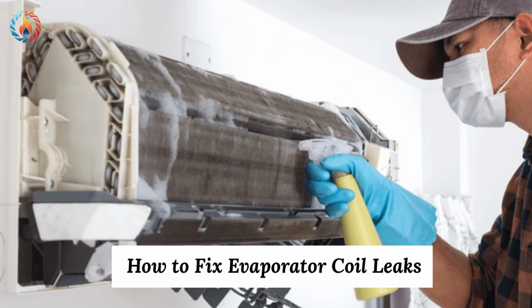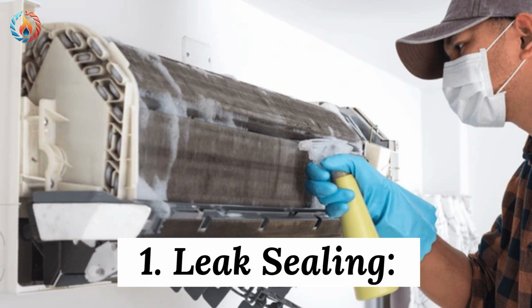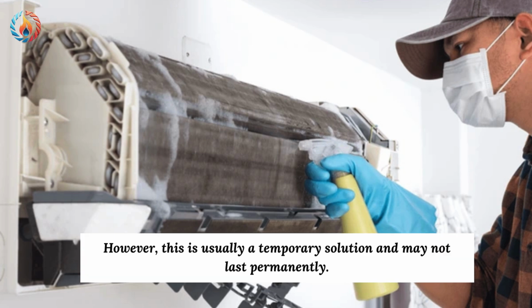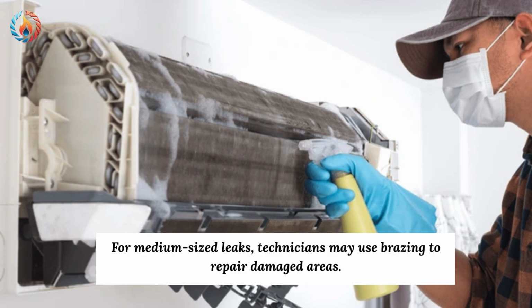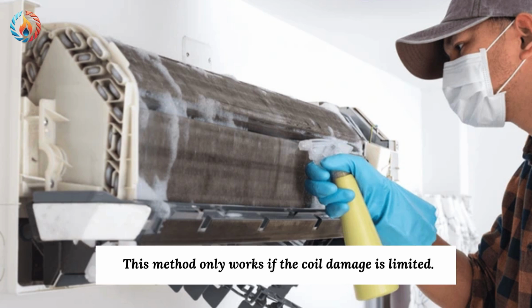How to fix evaporator coil leaks. Now let's discuss repair solutions. 1. Leak sealing. Very small leaks can sometimes be sealed using special AC sealants. However, this is usually a temporary solution and may not last permanently. 2. Brazing or welding. For medium-sized leaks, technicians may use brazing to repair damaged areas. This involves heating the copper and sealing the crack using filler material. This method only works if the coil damage is limited.